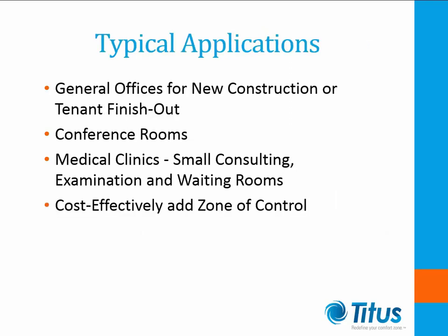Where would variable air volume diffusers be used? They can be used in large new construction projects or as a smaller finish-out work to provide additional local control. They offer one additional way to provide control and increased occupant comfort. Sometimes they can provide a solution for a local problem, such as a conference room or other rooms with highly variable use. They also can be a good solution for entire spaces when combined with controlled air systems.